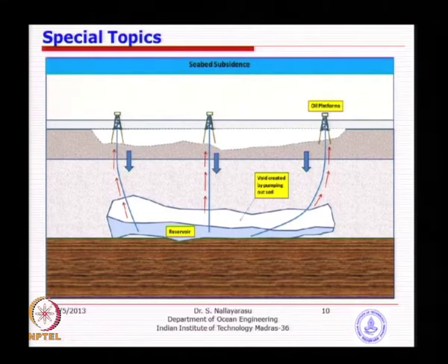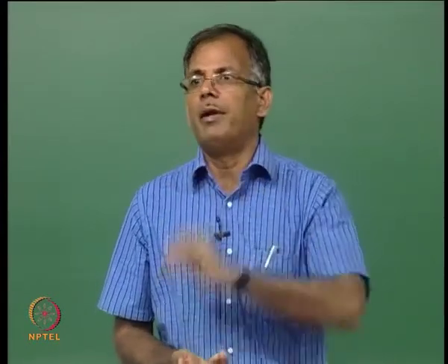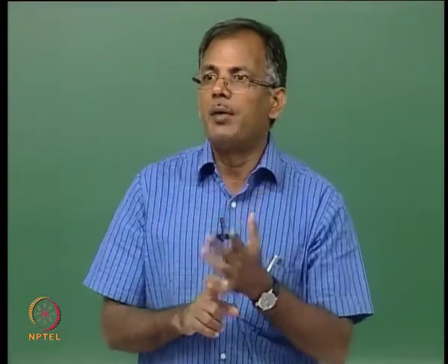It is not only the seabed, it is the complete layer on top of the reservoir that is going to go down. So, from the 90s to now, several platforms in the North Sea as well as in some parts of the Gulf of Mexico have gone down by more than 5 meters. Now, imagine, we discussed this problem in the design course, where the height between the underside of the superstructure and the water level is a minimum required depending on the sea state conditions. Otherwise, sea waves will actually hit the superstructure. One problem is the superstructure may not have been designed for that, and the amount of green loading, we call it green wave, hitting the superstructure will be substantially larger, which will make the platform fail instantaneously, because you have not designed for such a condition.